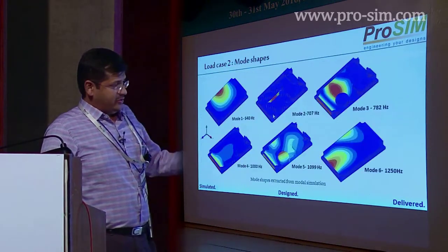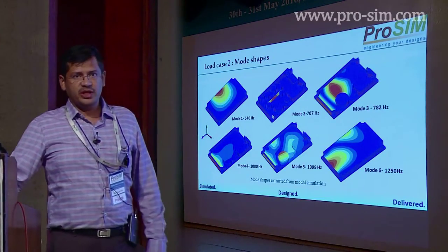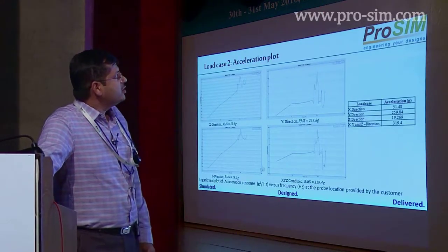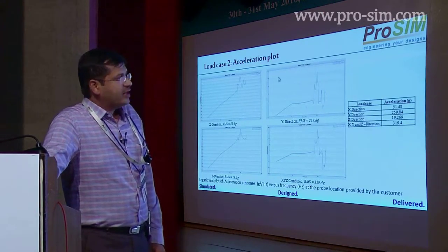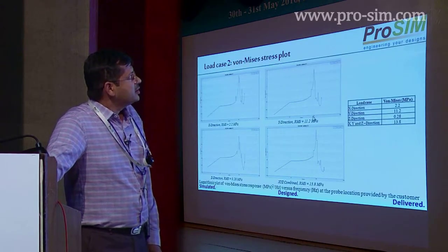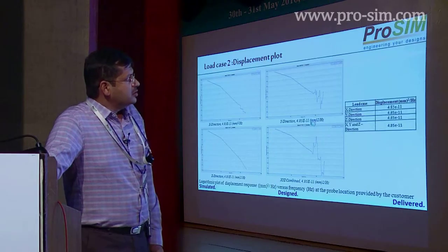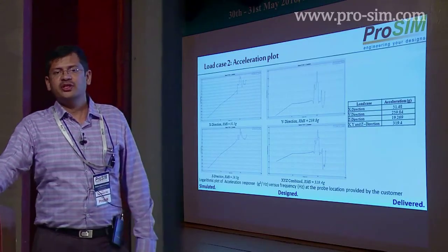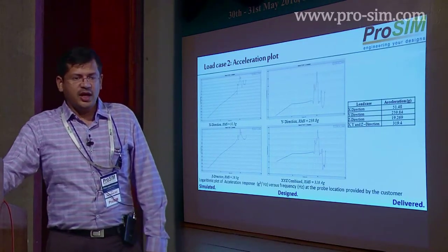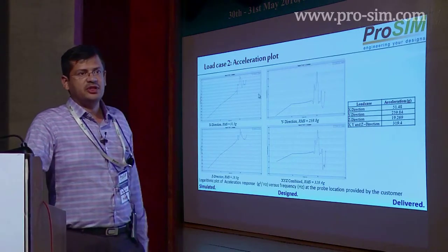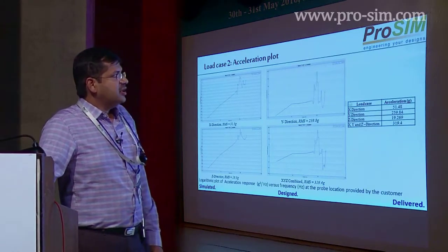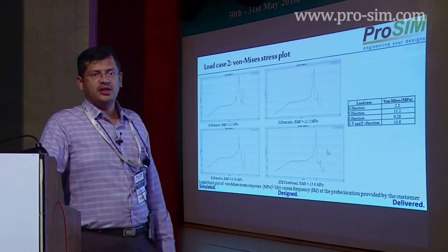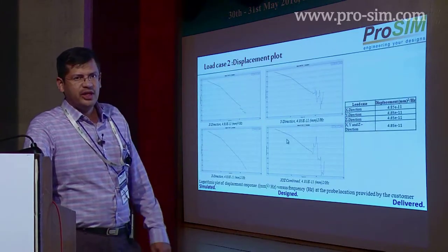So this, as I told, there were 3 probe locations, out of which we plotted the close to XYZ direction, and also the combined XYZ for acceleration, von Mises, and displacement plots. In all these 3 probe locations, we found that the second probe location was observed to be the peak location, and even that peak location I have just represented here as a snapshot, and this acceleration was plotted. Von Mises stress also was well within the allowable limit, close to 120 MPa, I remember.